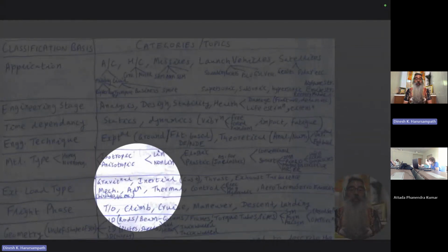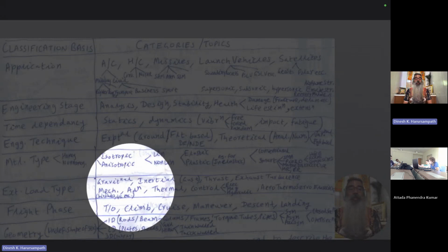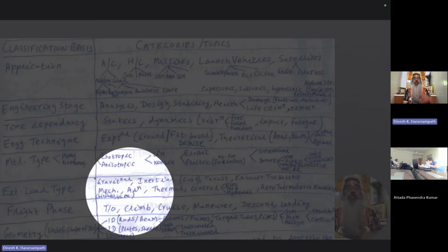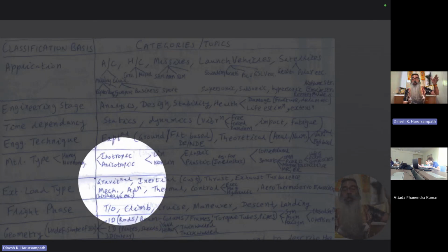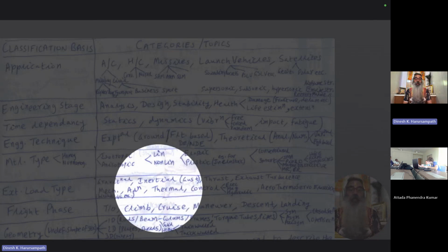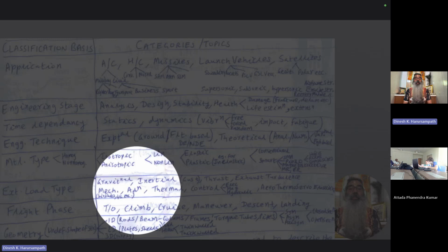And the most important thing, of course, is the aerodynamic load. What I referred to there is the aerodynamic load: lift, drag, the pitching moment, the rolling moment, the sideward force, which is usually very small, unless it's a helicopter, etc., which is tilting its rotor in one direction in order to fly sideways. Then, of course, the yawing moment as well. So all those things are the loads.